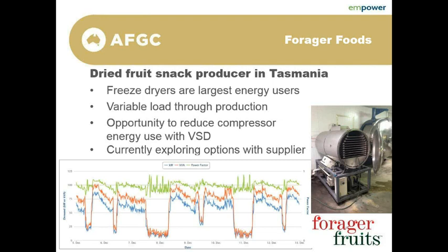Relative to the system they've got at the moment, it's about a 12% energy saving, or roughly $6,000 a year, against the cost of a VSD of around $10,000. So they would expect between a 1 and 2 year payback for fitting a VSD to their equipment. And that's currently what they're exploring with the equipment suppliers.